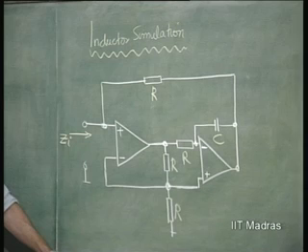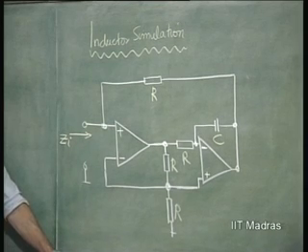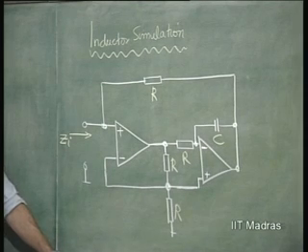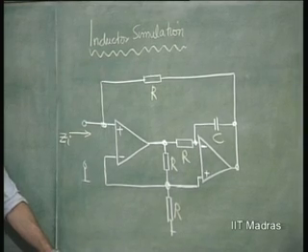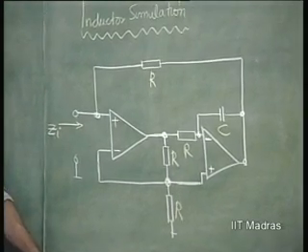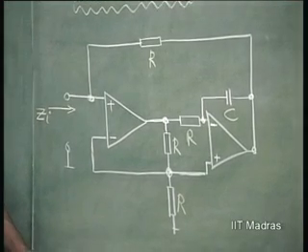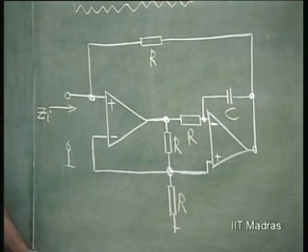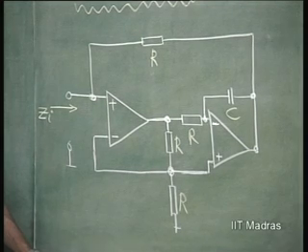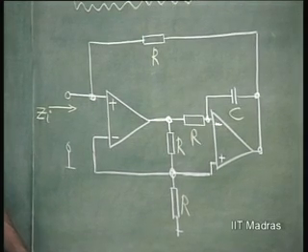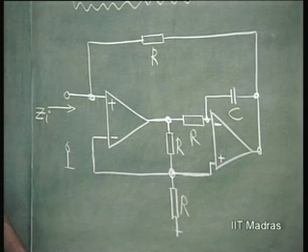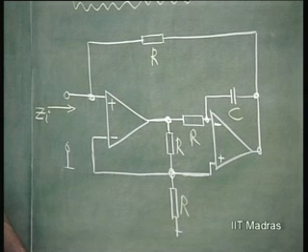So, let us now consider another important part of active filters, that is simulation of inductor. Now, this comes into picture. Inductor, for example, in the micro miniaturization becomes a very difficult component to deal with, the coil. In monolithic integrated circuit it is not possible to fabricate it at all. So, almost all circuits which are to be made out of monolithic IC require that inductor be not existing. Suppose therefore, we want to simulate such an inductor using resistors and capacitors and active elements.